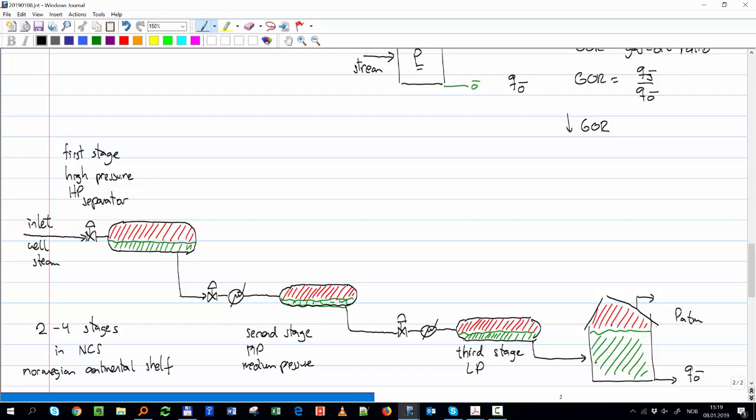So you can really see now where this Q oil is measured. Okay, you see, you go all the way after all the separation stages after the tank, and you measure how much rate you have there. And that's simply the rate, this standard condition rate that you're producing. Actually, that's the number people measure to calculate the revenue of the field. Okay, now let's follow the gas. Okay, with the gas always it's a bit more complicated.